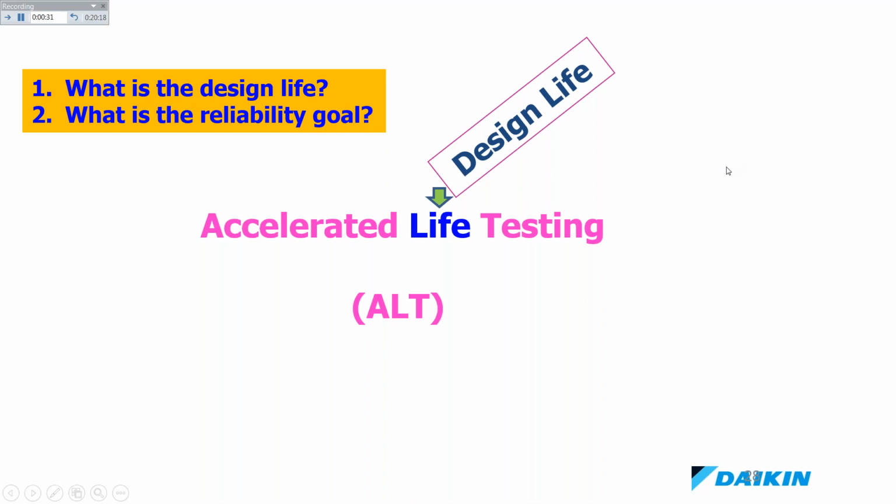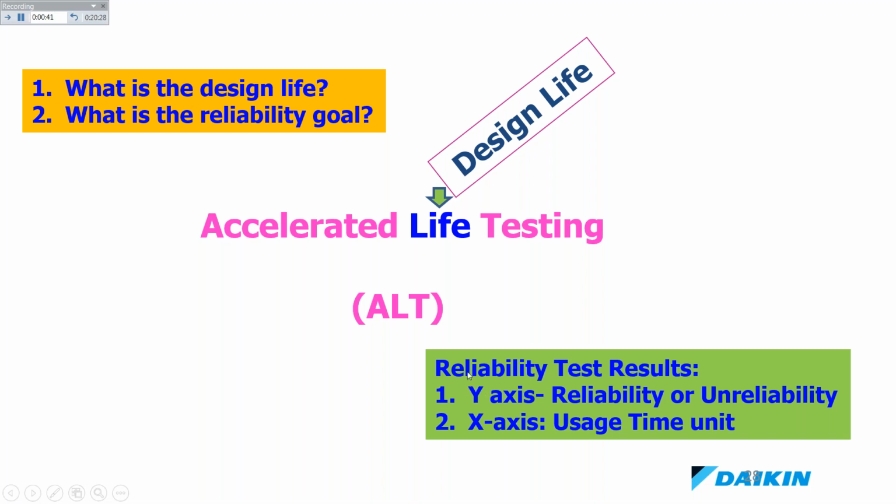So if somebody says, hey, we do reliability testing, ask, what's the life? What's the design life? What's the reliability goal? Always ask for a reliability plot. To constitute a reliability plot, the y-axis would be reliability, and the x-axis would be a usage time unit. If that doesn't hold, it's not called a reliability plot.